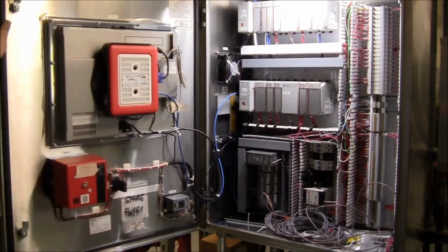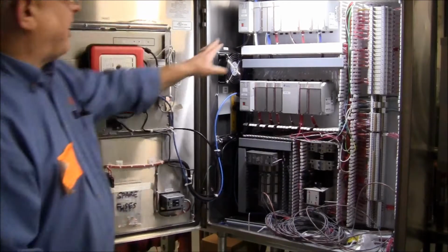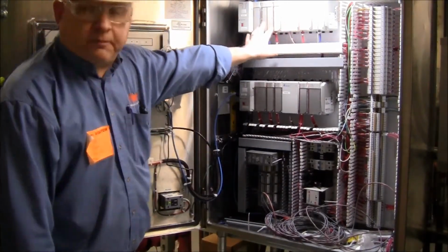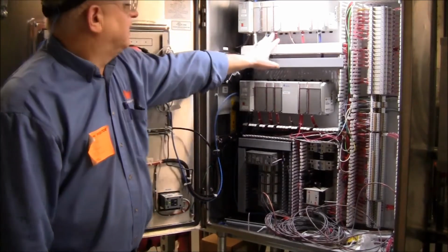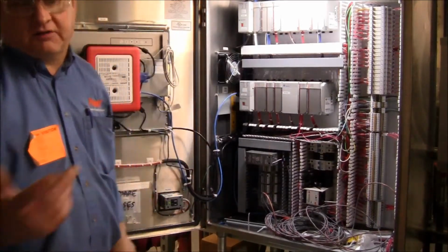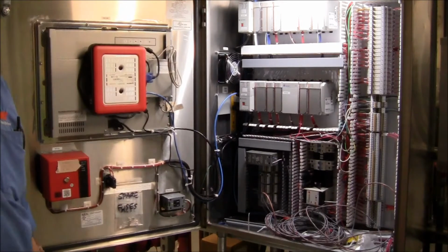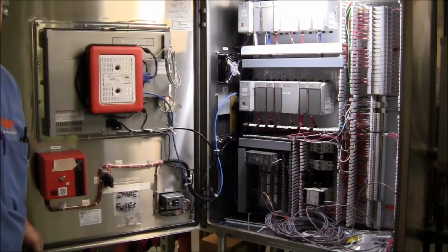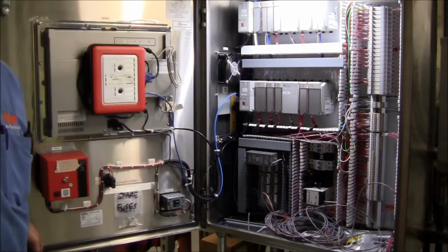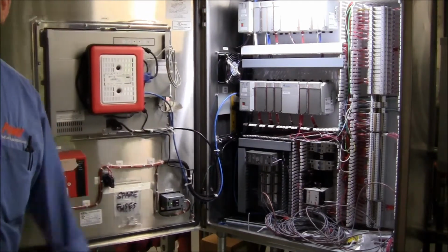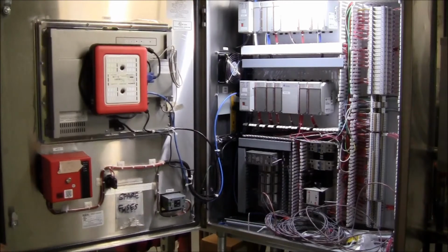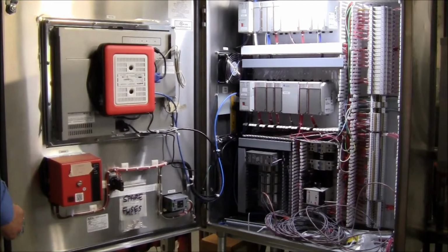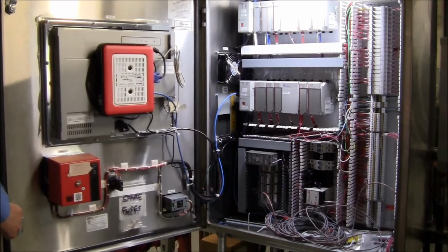And PLCs consist of a processor, a power supply, and peripheral cards that do different things. So you have analog input cards that take a 4-to-20 signal from a field device and go into the PLC. They can also have 4-to-20 analog outputs that can control things, like tell a valve what to do. And we have digital inputs that are switches for high limits, low limits, that kind of thing. We have digital outputs that are basically switches that can turn on a pump or a motor.